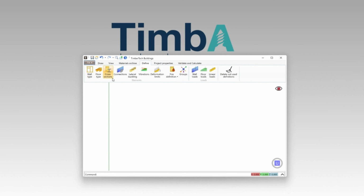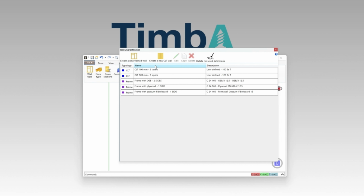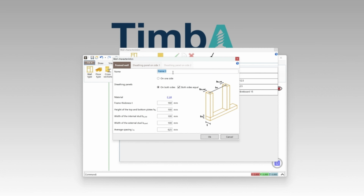Let's start with wall type. Here, you'll find default definitions for CLT and timber frame systems. Let's take an example of creating a new framed wall. First, give your wall a name. This helps later when you want to edit it or generate quantity takeoffs. Let's say we're working on external wall, first floor.